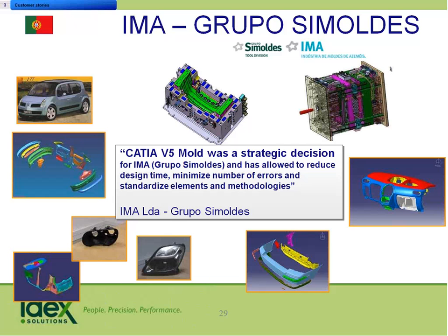So when we get into stamping of components, we can do this as well. We can run an analysis on how the part deforms. Autoform has their own thing that goes along with it. So does Forming Technologies. All these guys do spring back calculations and everything else. So we can actually take their information and have it deform the surface. In essence, we take the part, design it the way we want it to look when it's in use, but then we take that part from when it's in use and build the tooling off of it. So we need to change the tooling to account for the spring back or any deformation that might happen during the tooling process.